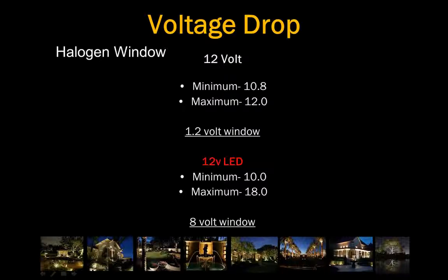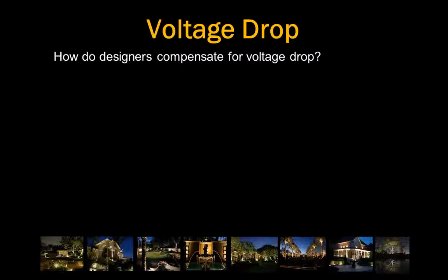Now, if I go below 10, that's when the LEDs will actually start to dim. And if I go above the 18, we'll actually short the LED out. It won't get brighter. You'll actually fry the electronics inside that LED.